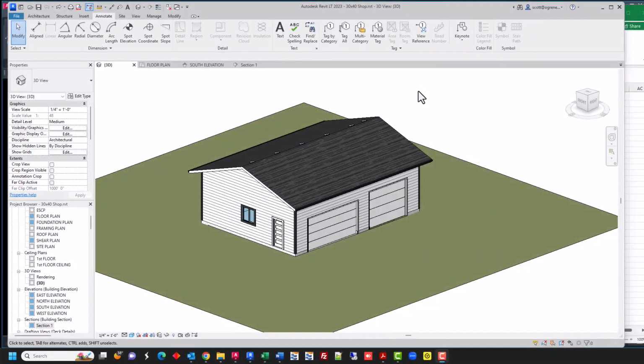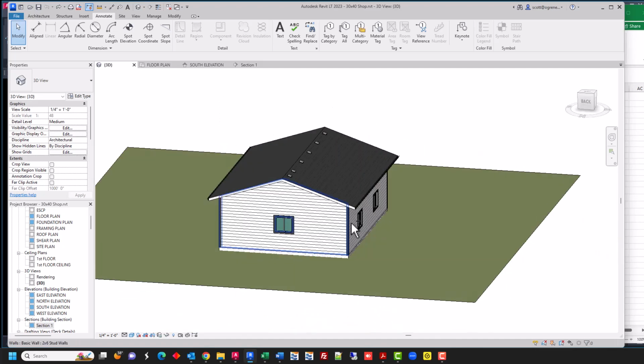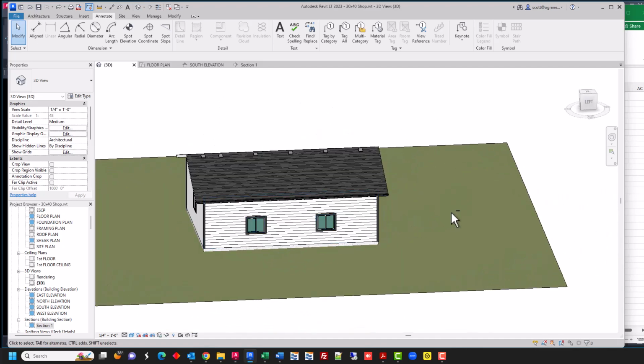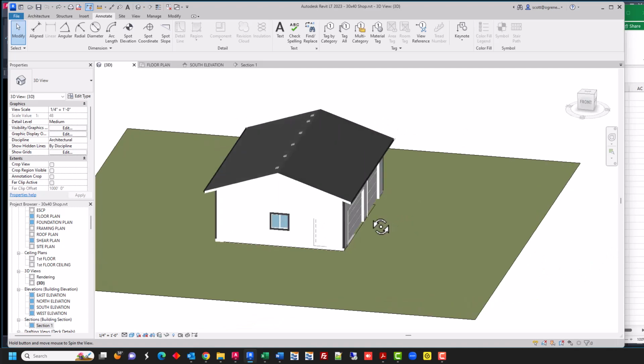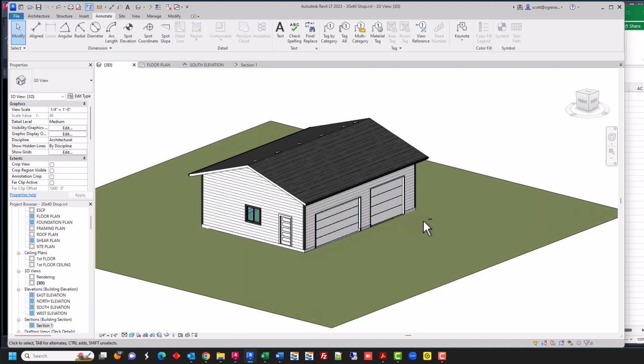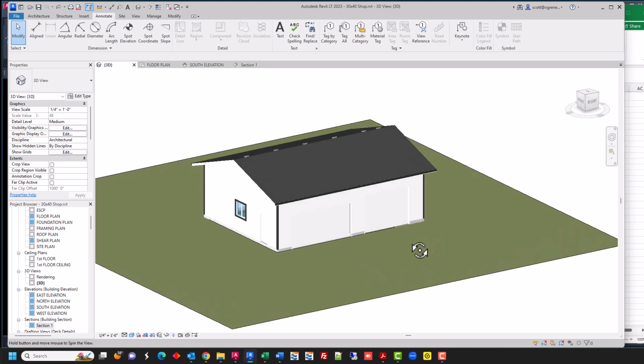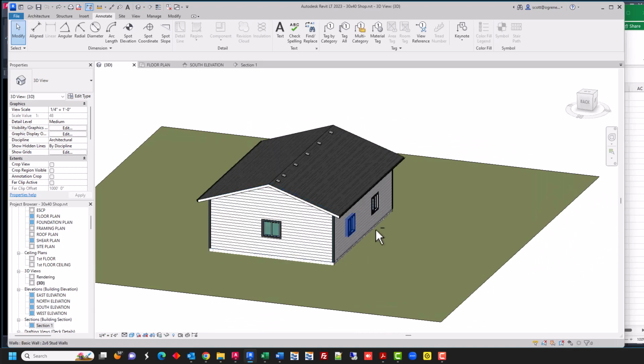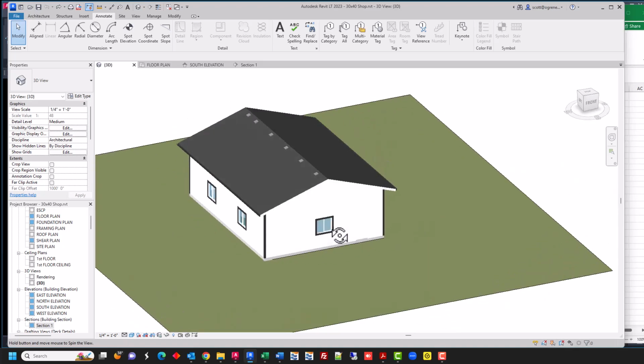What is Shearwall Pro? Shearwall Pro is software made for you, the designer, to be able to do your own lateral analysis on any building 4 stories or less that is wood framed and has a maximum of 12 grid lines total combined in both directions. Turns out that's almost everything you're going to work on.